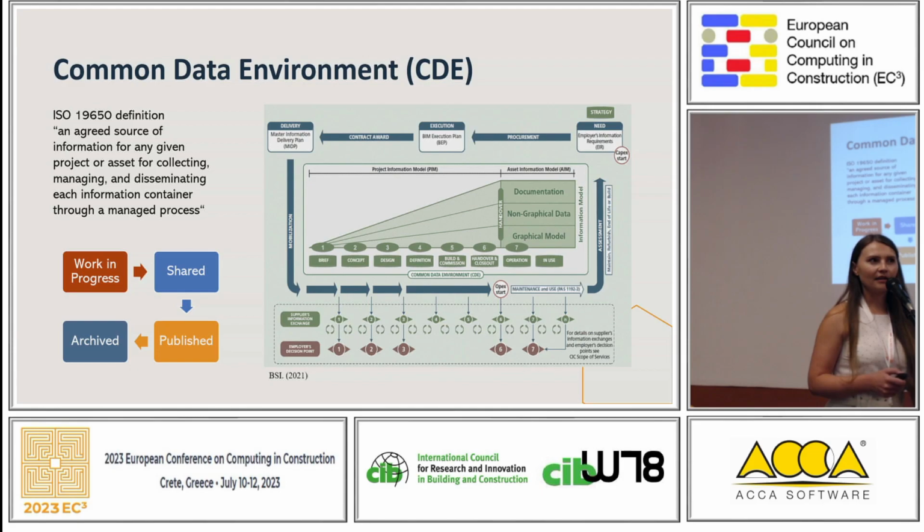A CDE can both mean the CDE solution, which can basically be software or a data storage where data is exchanged between the stakeholders. But CDE also means the CDE workflow, which organizes the flow of the information between the different CDE containers. So, for example, between work in progress, shared, published, and archive folders.